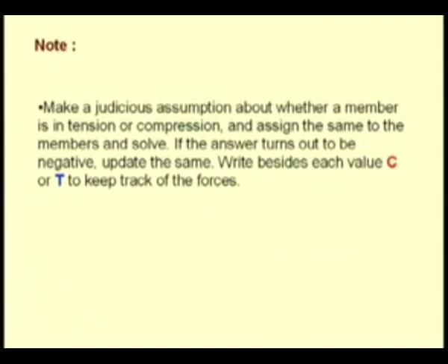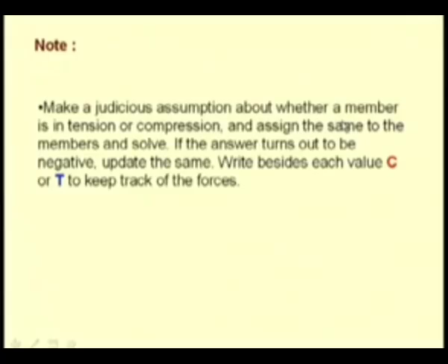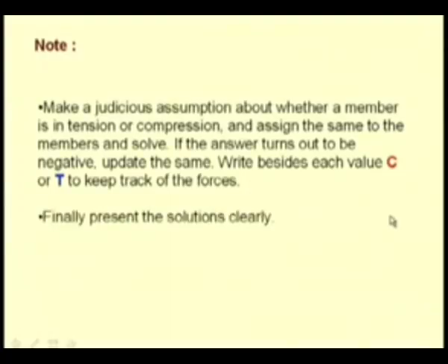Before we proceed to analyze, we have to assume the nature of the internal forces that exist. We have already seen that the forces can be either tensile or compressive in nature, and we have to assume either of these and accordingly depict the same. And after solving, if we find that the answer turns out to be negative, then we can update the assumption. That is, if we have originally assumed that the member is in tension and the answer turns out to be negative, then the member is in compression. Finally, we present all the determined forces along with the nature of the forces, that is either tensile or compressive.